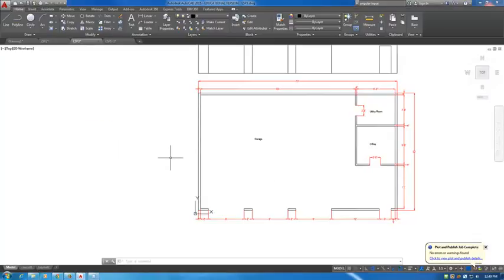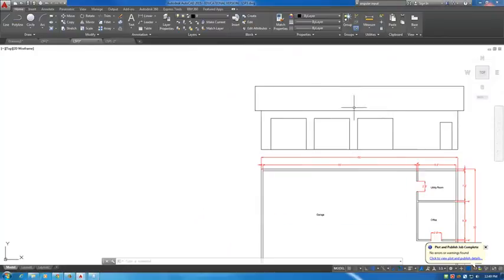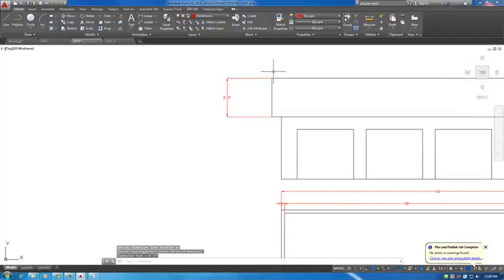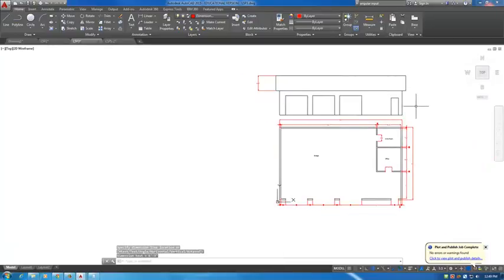Where that comes into play is on your roof here. That's how you draw the height. I'm going to dimension this right now on my dimension layer, just to see how high this is. So 6 foot 3 inches. I'll bet you I went with a 5/12 pitch on this. Let's try this.